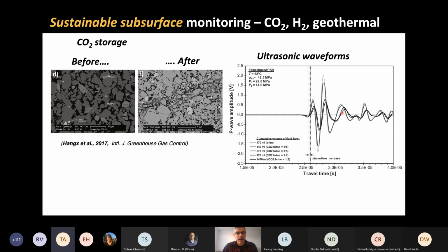Now, can we explain this somehow and relate it to the microstructure descriptors? Because if we can, that means that we may even be able to reconstruct, to recreate a fake sample of the microstructure based on something like this, remembering that these structures here are several times smaller than the dominant wavelength. These pictures that you see here are maybe 20 times smaller than the wavelength.